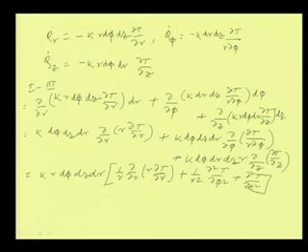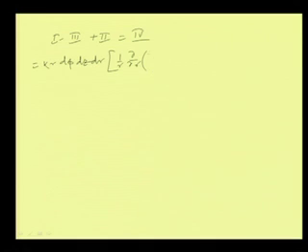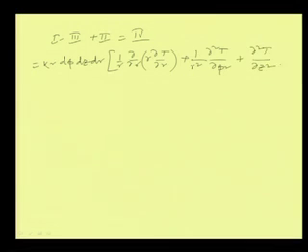Now, if we write 1 minus 3 plus 2 equals 4, as we have written in the previous case, then we will get k r d phi dz dr into 1 by r del by del r of r del T by del r, plus 1 by r square del square T by del phi square, plus del square T by del z square.